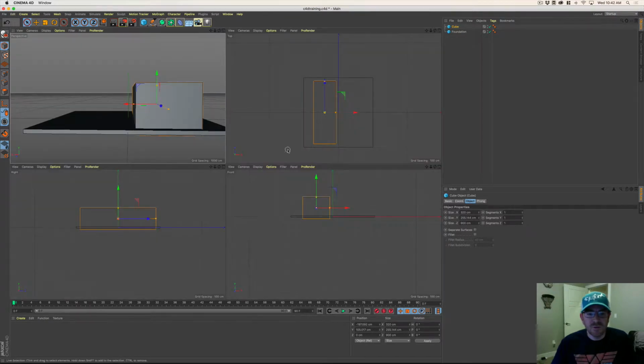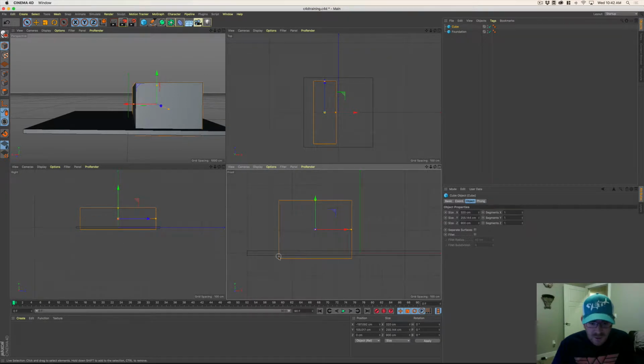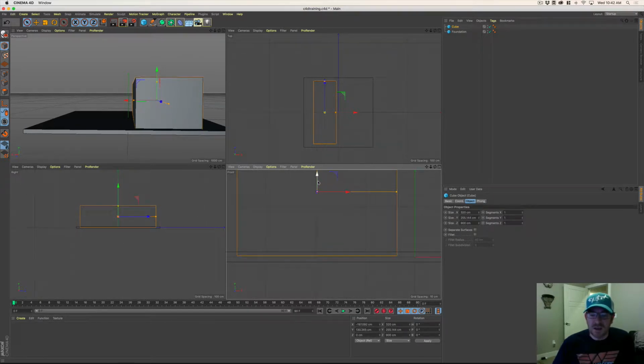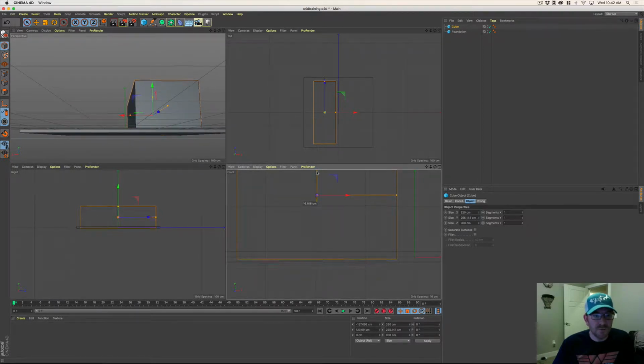One way you can handle that is popping into your 4-up view and taking a look and going, oh okay, the box is actually extending below the foundation. You don't need to have it line up perfectly. It can intersect, that's okay, as long as it doesn't stick below. So you can see right here, it's sticking below. Your 4-up view is a really, really critical tool in figuring this thing out. What I did right there, and I do it all the time, is I rotated my front view. And I hate that. I'm like, oh man, now it's all rotated. Anytime, you can fix that by going to View, Frame Default on any of these windows, and it resets it.